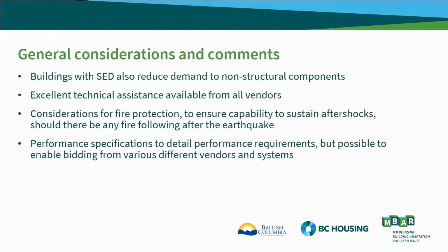So some general considerations. These also reduce the interstory drift, the deflections, and the demand to non-structural components. The vendors that I listed before provide excellent technical assistance to the structural engineering community. One can consider fire protection of these devices to ensure their capability to sustain aftershocks, which usually happen should there be any fire following after the earthquake.